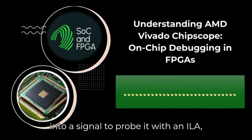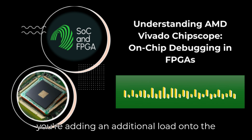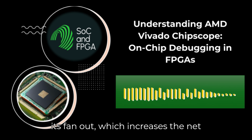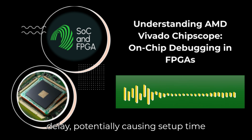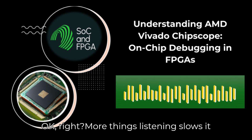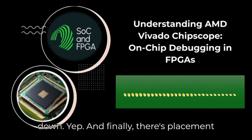Exactly. Another factor is increased fan-out. When you tap into a signal to probe it with an ILA, you're adding an additional load onto the net driving that signal. This increases its fan-out, which increases the net delay, potentially causing setup time violations on paths that were previously okay. Right, more things listening slows it down. Yep. And finally, there's placement disruption.